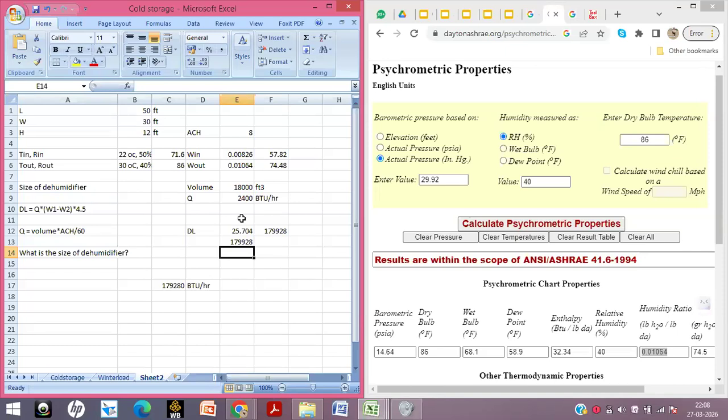We need to calculate the total heat loss through walls, windows, roof or ceiling, and floor, plus infiltration and people heat gain. From that we get the net heat load, and convert BTU per hour to kilowatt, so that we get the proper heating coil size.